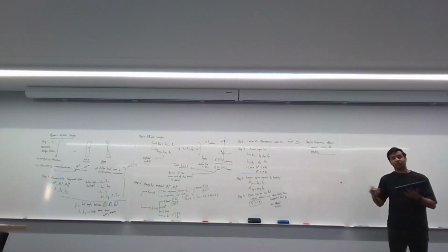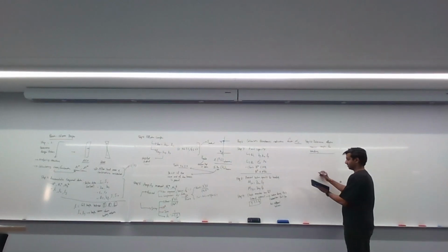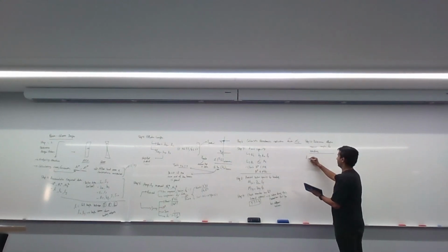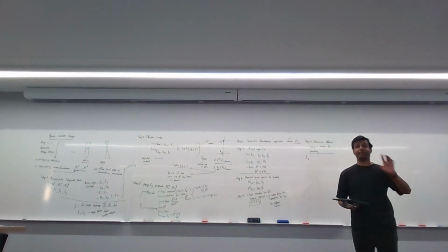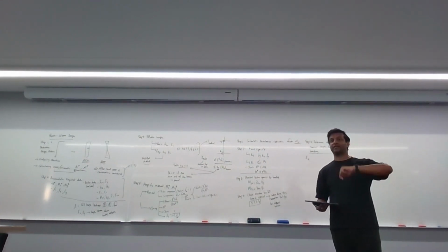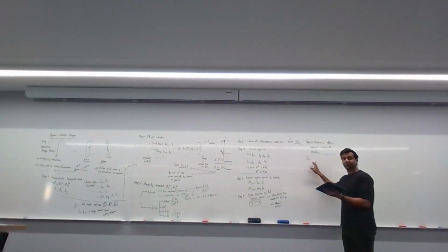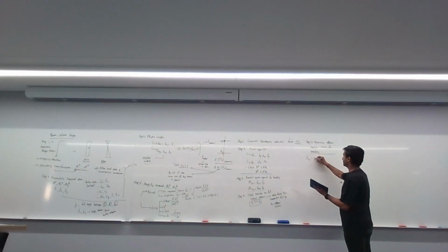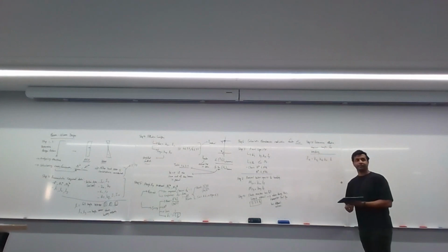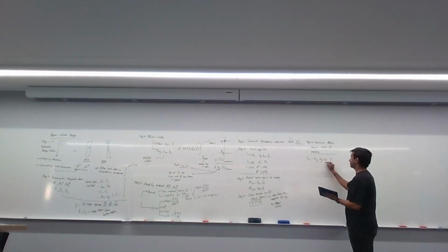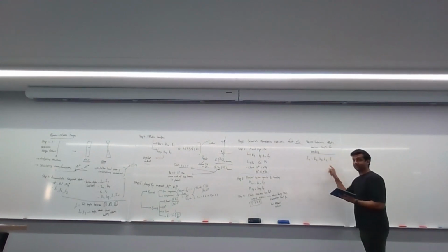Okay. Now when you're determining the effective member length for bending, the couple of things that you need are the effective length for bending, LE. This is different from the gamma method effective length. Remember, the gamma method effective length was to calculate the effective length for compression. But now when we're looking just at bending, we've got a different set of rules to deal with. Remember, this is KT, KL, KR times the length. Okay? We use the appropriate tables to calculate what these values are.